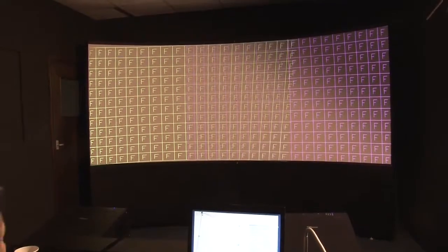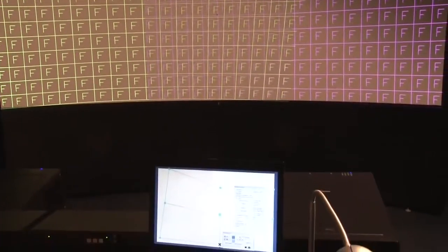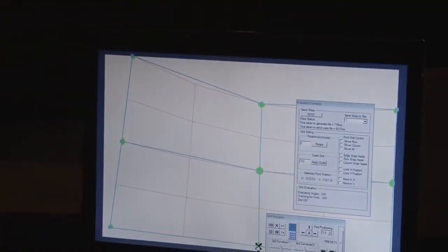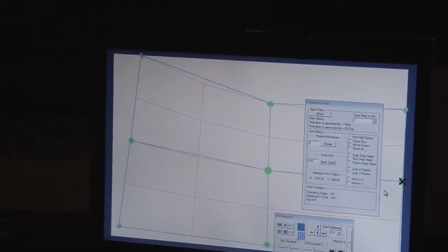It's not looking bad in the left and the centre of the left-hand projector, but the top right corner still needs some attention and it still needs a bit of squaring up. So now we're getting fairly square at the left-hand side. You can see the linearity is not quite right yet. That's something we have to deal with once we've got the picture shape roughly right.